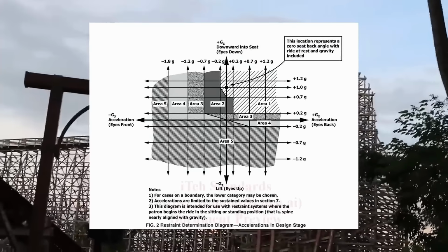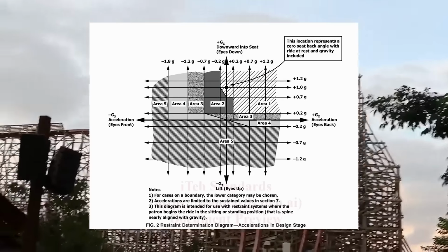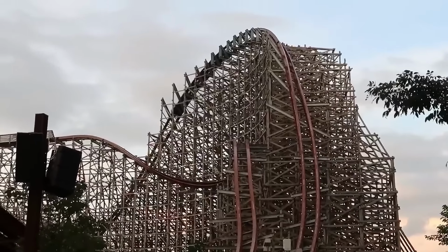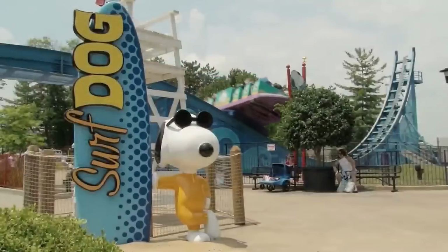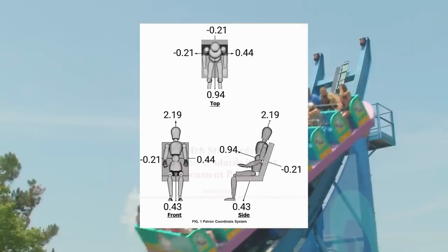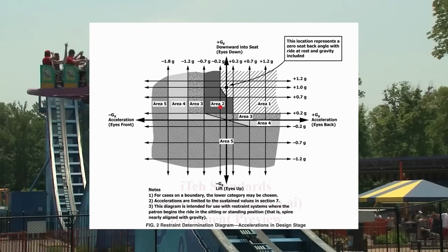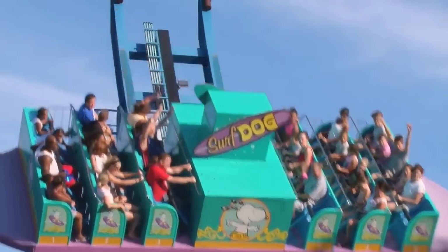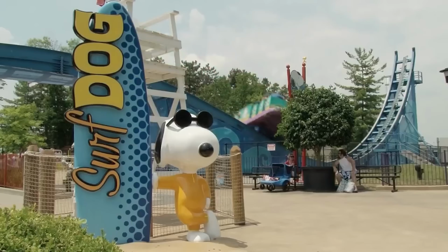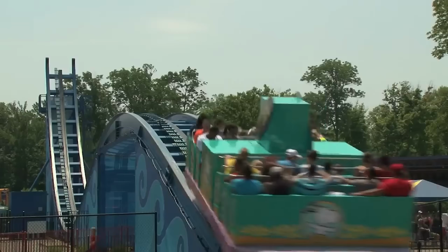Ride manufacturers must calculate the G-forces their rides will subject riders to and plot them on this graph to determine the minimum qualities of their restraints. Let's do a quick example with the Zamperla Skater coaster. Plugging in the recorded G-force data from the ride recorded by G-Force Productions, we can see that this ride falls under Class 2. Examining the ride, we see that it uses 1 lap bar for 6 riders that can lock in multiple positions and is not redundant. This makes it a Class 3 restraint, making it more compliant than it needs to be.